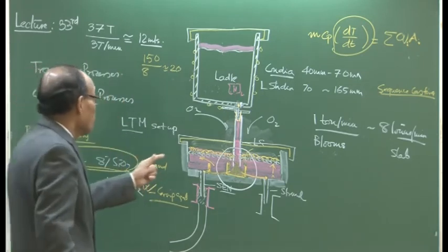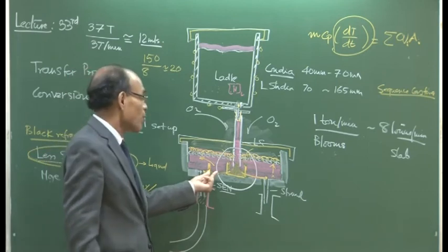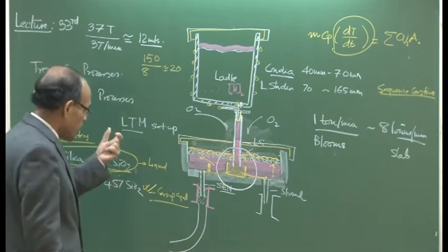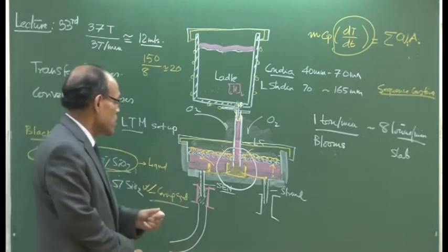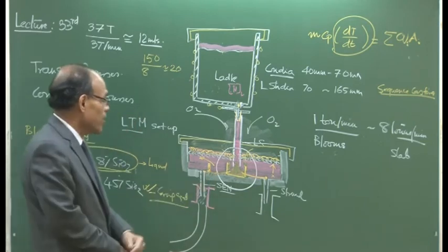The tundish will be fitted with what is known as flow friendly refractory artifacts, which are made of castables or high alumina bricks, which can sustain the flow pressures and do not undergo much degradation in terms of erosion etc., contaminating liquid steel.